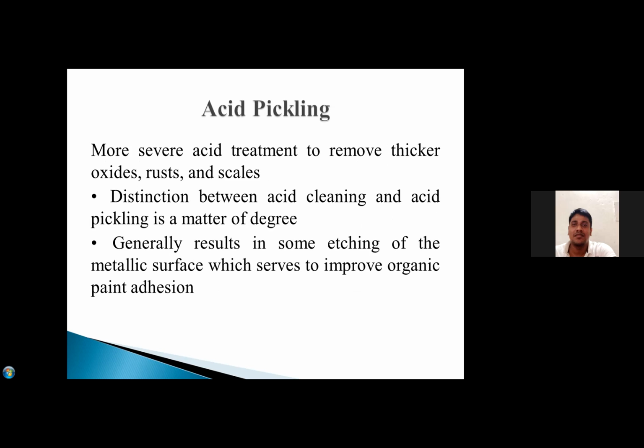Acid pickling. It is used to remove thicker oxide, rust, and scales. The distinction between acid cleaning and acid pickling is a matter of degree. This generally results in some etching of the metallic surface, which serves to improve organic paint adhesion.